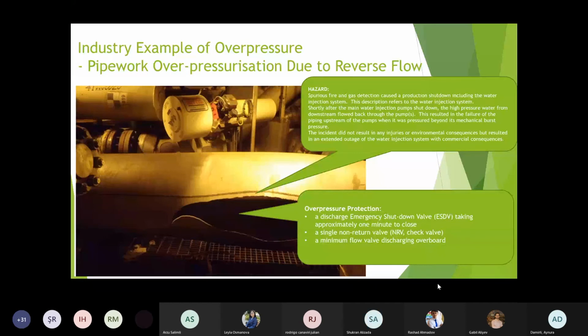They were not identified as safety critical. Again, this is one of the problems we had previously and currently in our facilities, and they were operated to failure. Upon a pump trip, these valves open when the measured flow rate falls and provide a path to the pressurized system. In the absence of a relief valve, these are the most critical barrier to preventing overpressure.